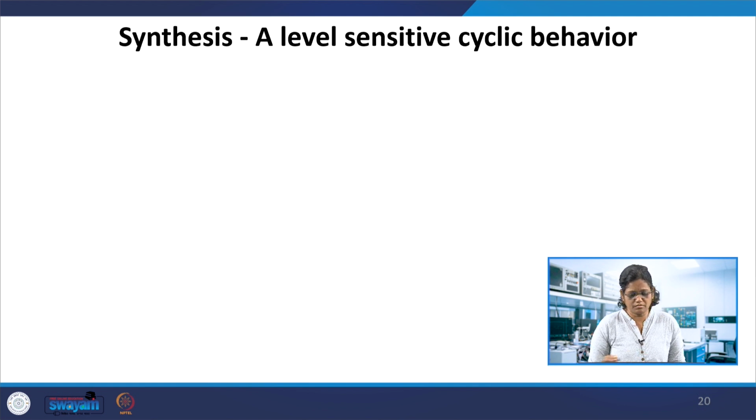And then the third category, which is synthesized into combinational logic, is a level sensitive cyclic behavior, always at the rate of what is in the sensitive list, which is level sensitive, not edge sensitive like in the flip flops.